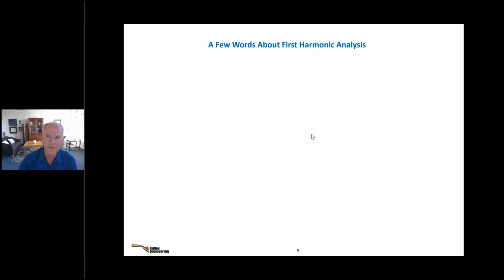I will follow convention here, and the industry people will groan because they don't like first harmonic analysis, and the academic people perhaps will go, oh yeah, first harmonic analysis. My few words about first harmonic analysis are: you don't need to do this. You don't need to do it. If you're putting first harmonic analysis in your LLC design these days, you're reinventing the wheel.